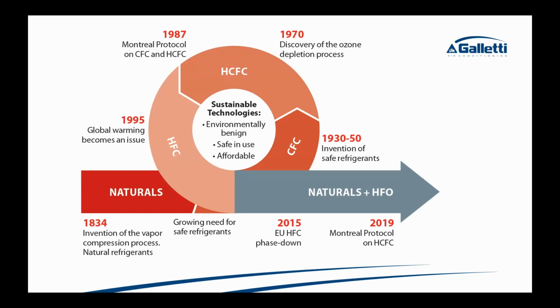So the fact that the DOE did that with Copeland last year, and given how everything else is progressing, it really only leaves, for reasonably low ambient, once you factor in the PFAS, R32 and R290. And even R32, we're still in the 600s for GWP. So technology's trying to adjust as quickly as it can, but policy is changing very fast.